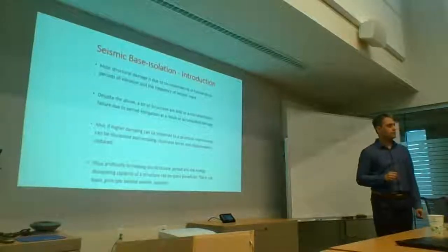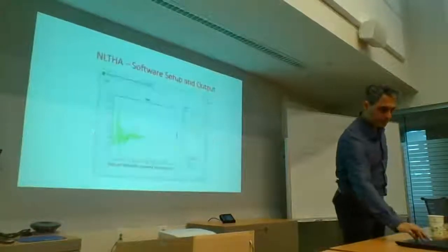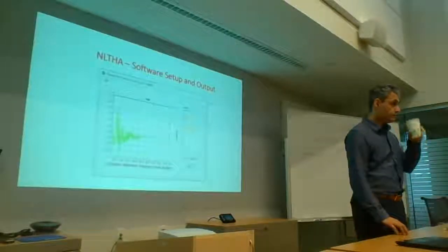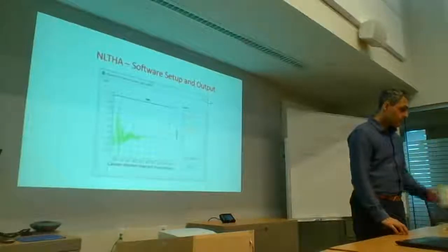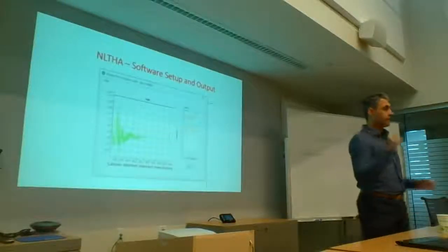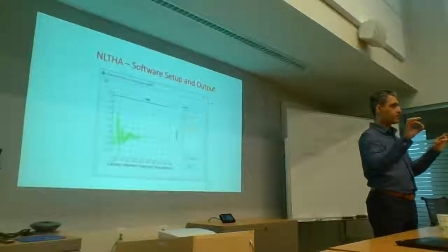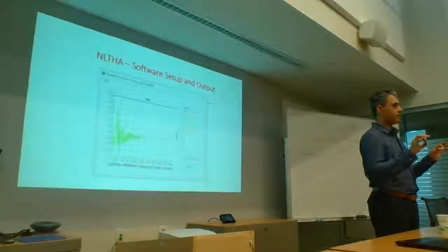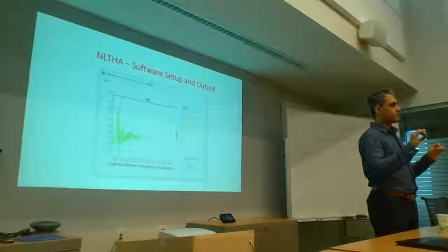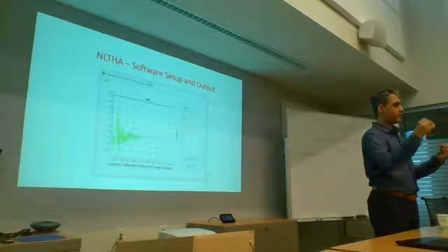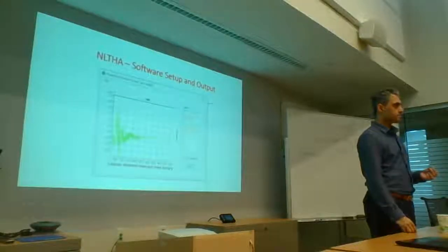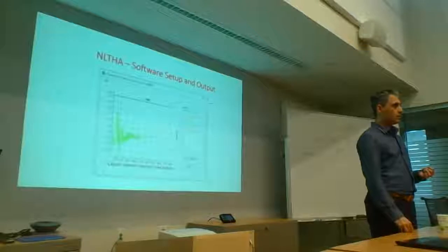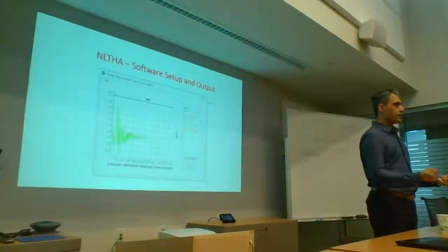Yes? It's the question actually previous slide. Yeah. You apply this support excitation. So you apply the acceleration at the support point or the displacement? Because this software cannot apply different time histories at different supports to acceleration, we asked the geotechnical engineer to give us displacement time histories. Because it's able to apply displacement time histories, different displacement time histories at different supports. So with time you apply different displacement at the base. Yes. And based on that, so there's no mass, nothing. Only the direct displacement. Yeah, it's a direct displacement of the ground.